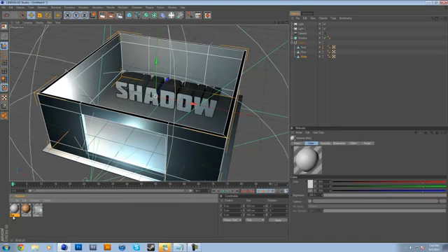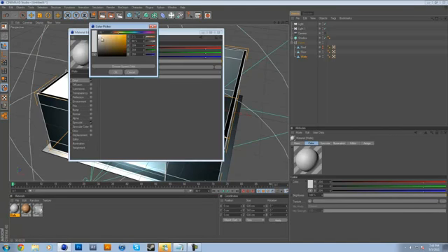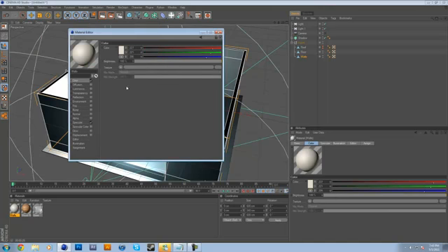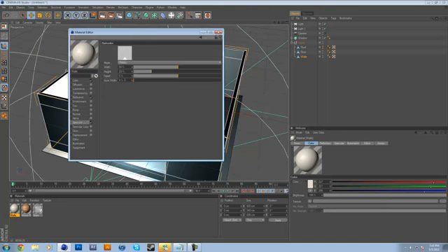And our final texture, which is going to be the walls, so I'll name that walls. For the color, I want just a really slight creamish sort of white color. I think I'll go for about 6% reflection again. Our specular, we can change that to about 45-15 again. We don't really need it because we don't want harsh, sharp stuff going on the walls. I'm actually going to turn that down to about 10.